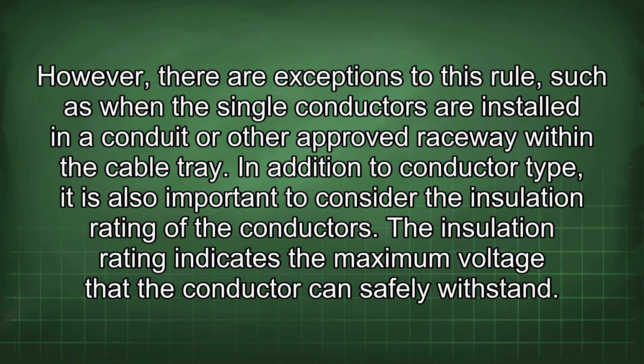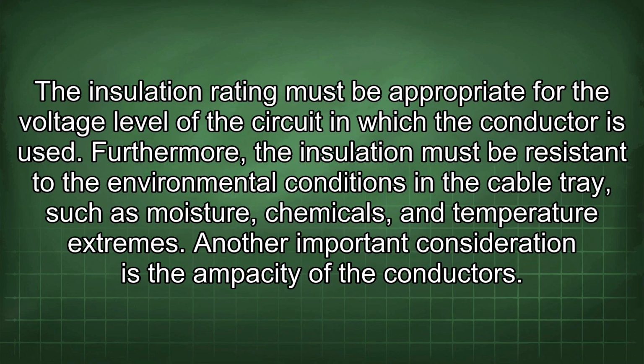In addition to conductor type, it is also important to consider the insulation rating of the conductors. The insulation rating indicates the maximum voltage that the conductor can safely withstand. The insulation rating must be appropriate for the voltage level of the circuit in which the conductor is used. Furthermore, the insulation must be resistant to the environmental conditions in the cable tray, such as moisture, chemicals, and temperature extremes.